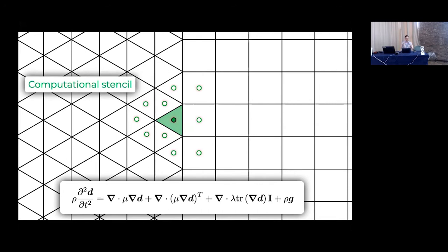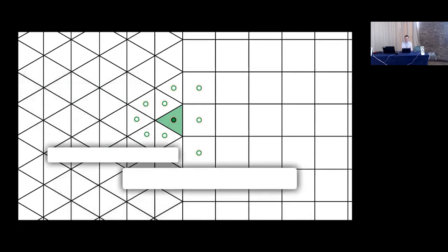So to enforce the equations on that volume, that area, we're going to write this equation below in terms of the unknowns at those points there. So that's one stencil. You can have different formulations for different size stencils, but this is a typical cell-centered one. So that's the stencil and the control and the integration volume.